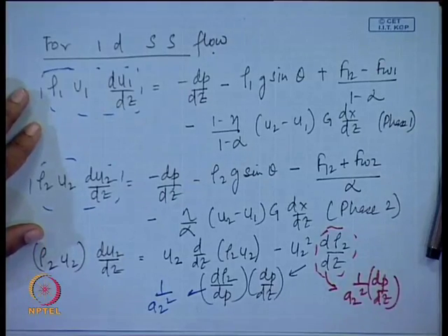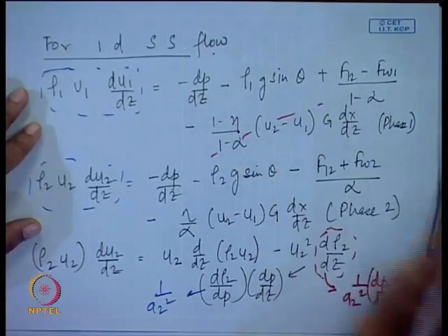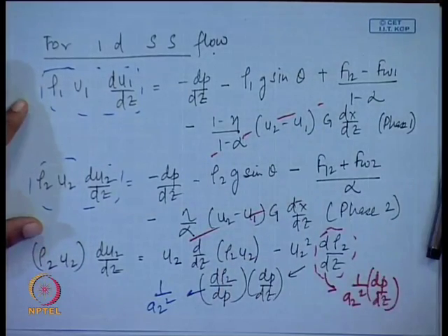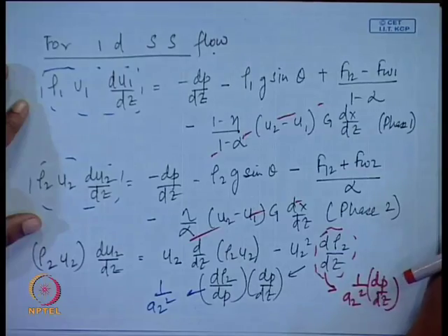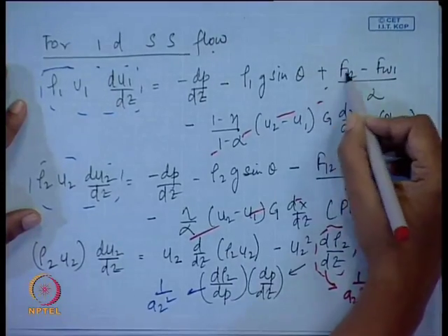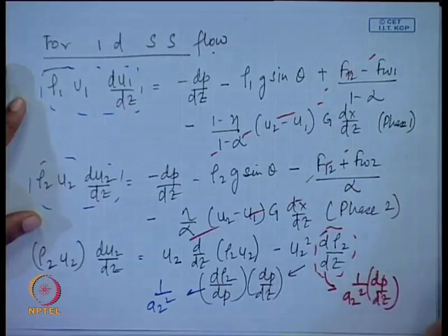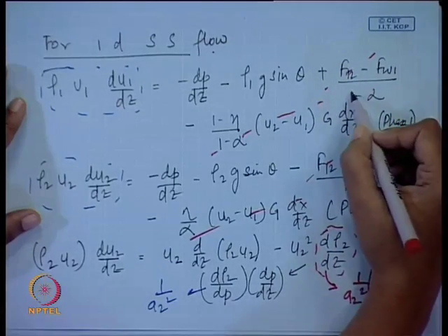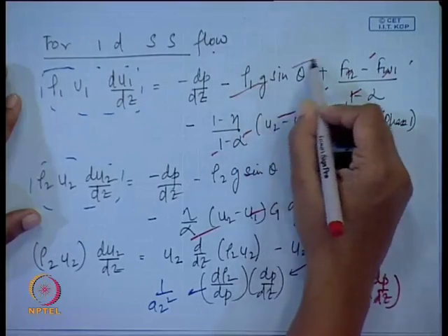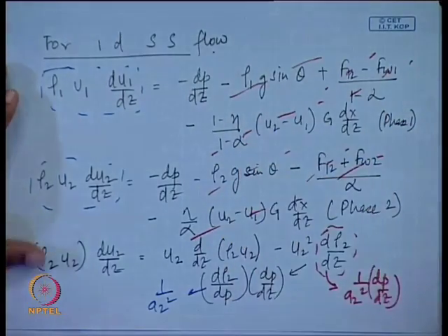So, under that particular condition, there is no change of phase, so dx dz terms cancel out from both the cases, yes or no? And since under these particular circumstances the phases more or less do not interact, the interaction between the phases is not very important, neither is the interaction with the walls very important, correct. If it is a horizontal nozzle, then naturally the gravitational components also disappear.